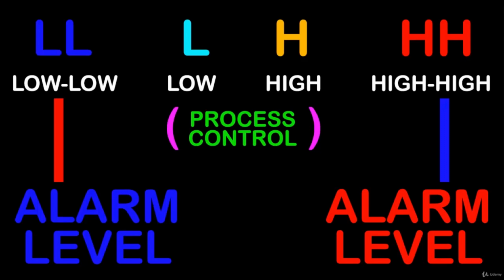So if the water gets too high on the tank, it just spills out into another tank which has another set of level controls. You don't always need all four of these, but it is important to understand when you should have an alarm condition.